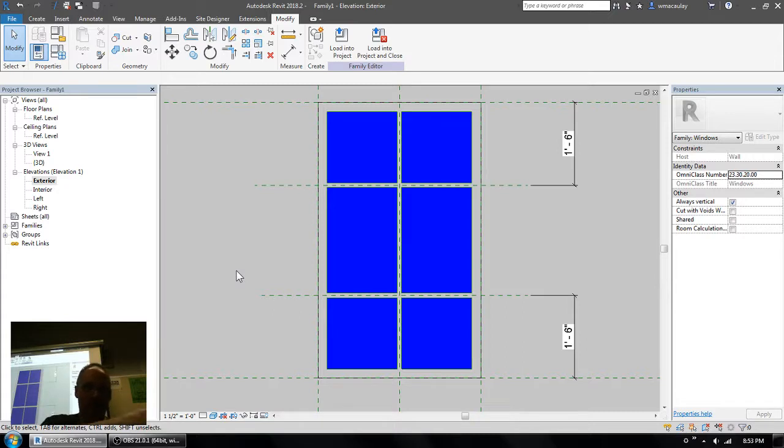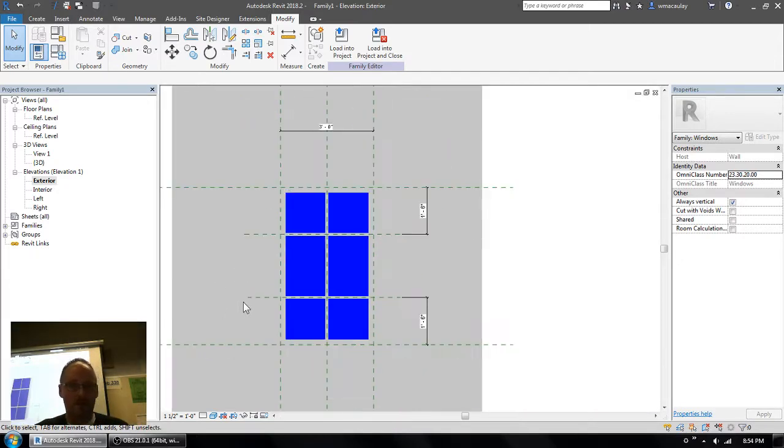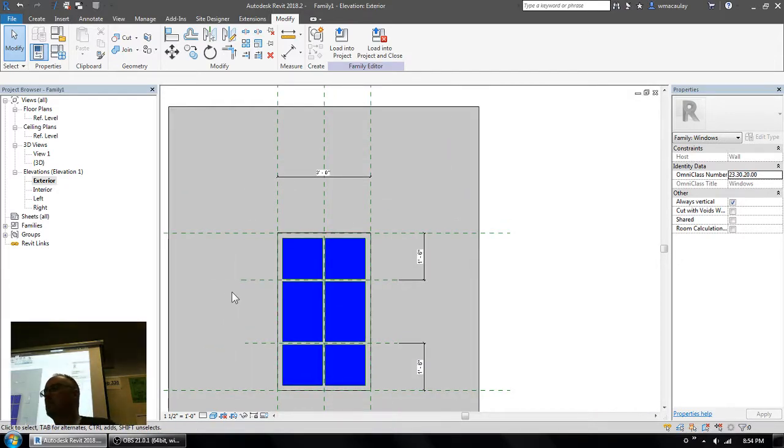Right, folks, so that is the end of the lecture for tonight. Maybe I'll just spend a couple moments here talking about flexing. This is good practice to do after you've made your own family. You want to use the family types dialog box and just see what happens when you put in some different values for the family. If I make it a little bit bigger, if I make it a little bit smaller.